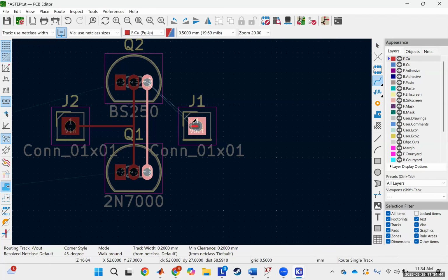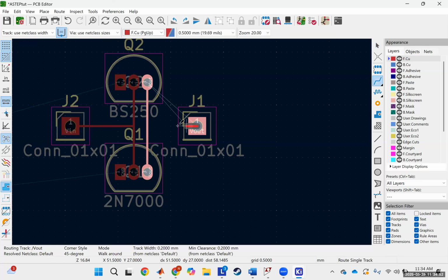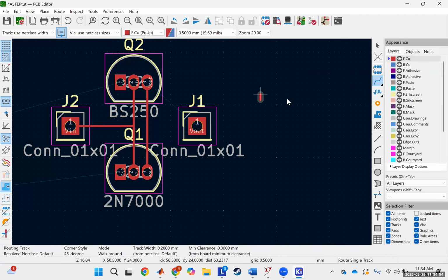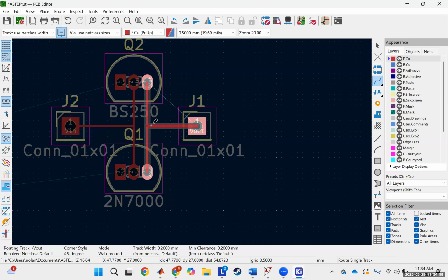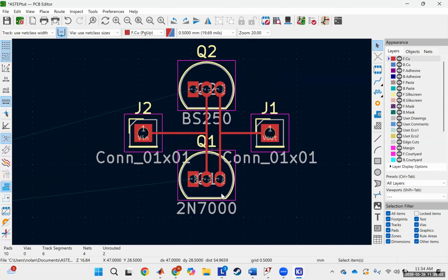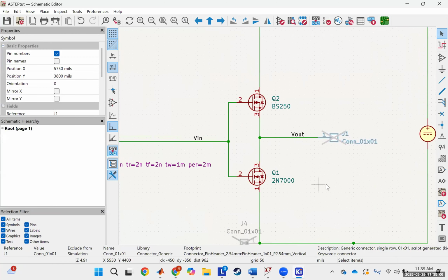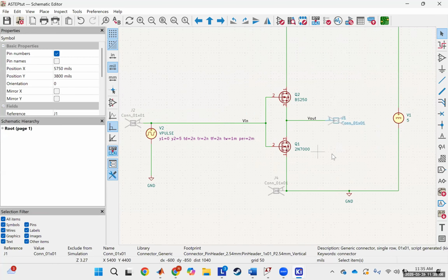And then you'll want to press X or grab your tool from the side again. Remember, if you press X, you want to put your cursor over this to start because it'll start you off wherever you press X. But you can press escape if you end up there. So connect this over here. And then now, to relate this to our schematic, we basically have our inverter finished.